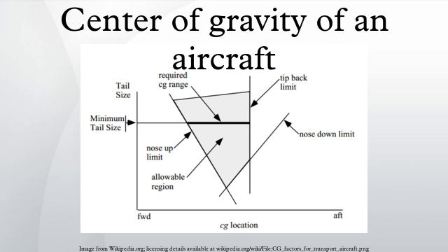Improper balance of a helicopter can result in serious control problems. In addition to making a helicopter difficult to control, an out-of-balance loading condition also decreases maneuverability since cyclic control is less effective in the direction opposite to the CG location. The pilot tries to perfectly balance a helicopter so that the fuselage remains horizontal in hovering flight, with no cyclic pitch control needed except for wind correction.